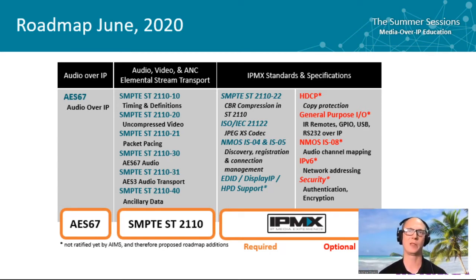So we're really looking at EDID. We're not just looking at EDID and thinking, okay, how can we squirt this through IP? We're really re-looking at this. We are architecting this with a goal of making EDID transparent through that API. So we want to make sure that people can get the raw EDID information, but we're also thinking about, in a multicast world, how do people want to deal with connections? What does a dynamic connection look like when the network starts going wonky or what have you, right? But right now it really is about EDID.